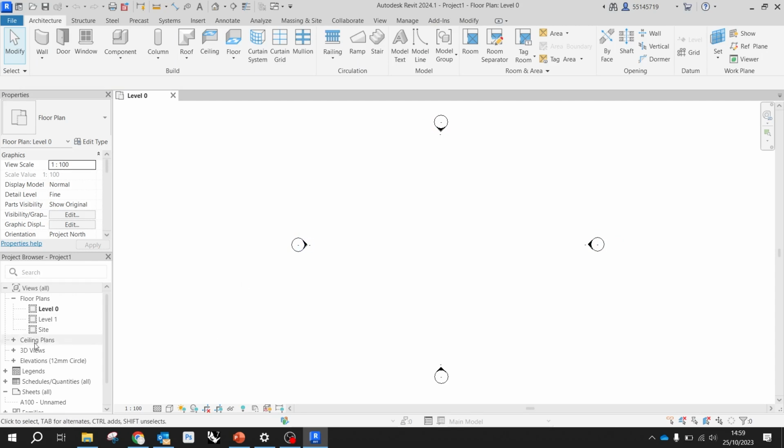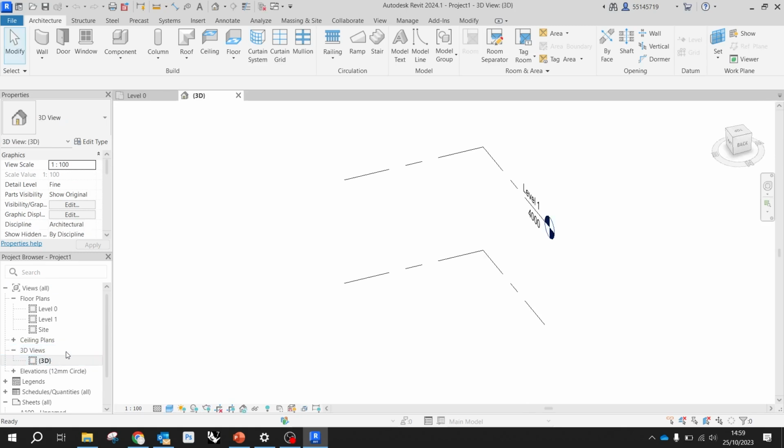There is not much. If I scroll through the project browser in here, which is where I can pick different views, I can open 3D views. I see that I do have a default 3D view. I can double click on it, that will open it. Now in here, I see that I have a couple of levels that are preloaded, obviously something that I can change. And this also brings in the question of how do I navigate in the scene in Revit? When you have the 3D, you will see that you have this view cube that is now being used in pretty much every Autodesk software.